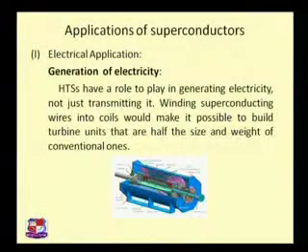But the change in flux will also result in current, and that current creates a problem with the resistance, that is I squared R T, the Joule effect. As the current increases, I squared increases, and the coil shows resistance, and due to that loss will be there. On the other side, eddy current losses are also there, and hysteresis losses are also there, which you already studied in 12th standard. So how do we solve that problem when we are generating electricity?